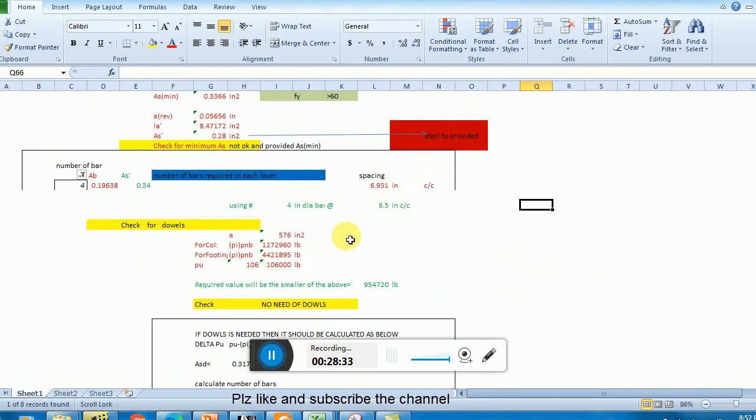And here I have dowels. Remember, we check whether we need dowels or not, because we provide dowels to safely transfer the bearing stresses. So this is the area of column, and we don't have this one, we have 12 cross 12, and this is calculated by formula.